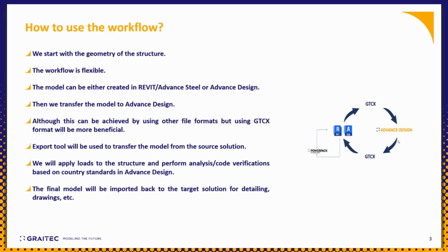Through this workflow, all of the loads, even if you have defined some loads in Revit, will also be transferred inside Advanced Design. And going back from Advanced Design inside Revit, all of the internal forces in your beams, columns and slabs, as well as, if you have done a concrete design, all of the required rebar areas will be transferred inside Revit.